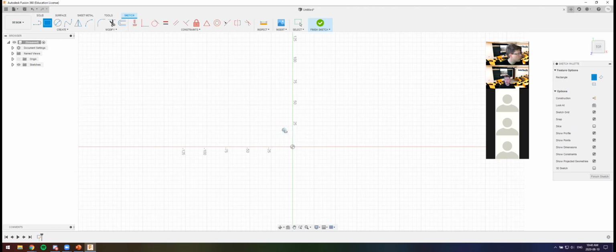All right, guys, one important thing to note about Fusion 360, something a lot of kids will get confused about when they're first using it because they're used to using Paint or PowerPoint or something. When using the tools, very rarely will you drag your mouse. You'll never click and hold the mouse. Usually you're going to be clicking somewhere and then clicking somewhere else, especially when you're sketching.